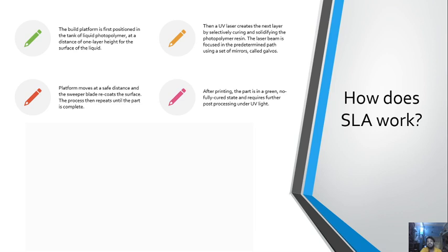The liquid resin is solidified through a process called photopolymerization. During solidification, the monomer carbon chains that compose the liquid resin are activated by the light of the UV laser and become solid, creating strong, unbreakable bonds between each other. The photopolymerization process is irreversible, and there is no way to convert the SLA parts back to their liquid form. When heated, they will burn instead of melting.